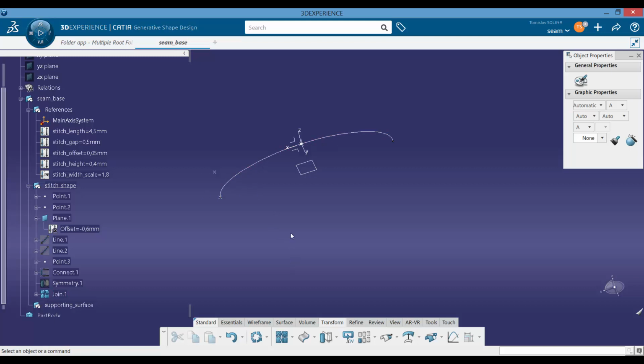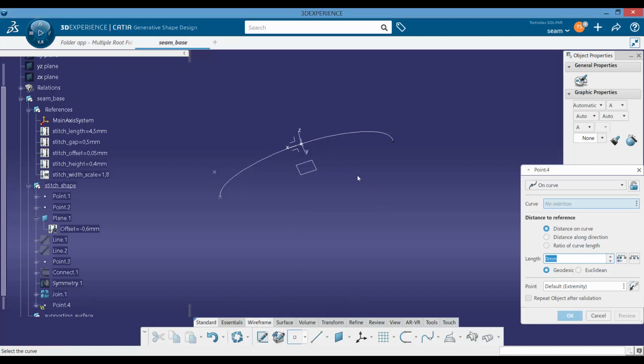for a stitch. But before this we will have a couple of other actions, so let's see how this has to be done. We will need one point where this stitch itself is coming out, so it won't start from 0, 0, 0, or it will be moved slightly behind, and it will be of course 0.65 millimeter below. So let's add those 2 points. We'll need both later, so let's create a point. First point is